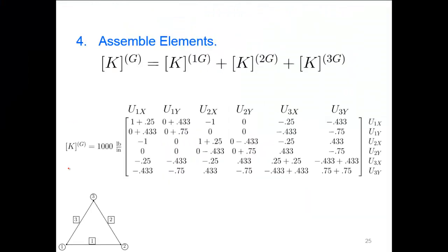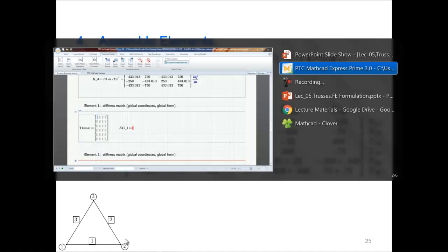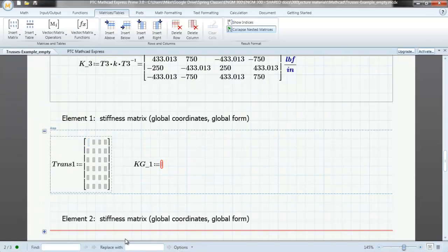Maybe let's go, yep, so we'll see right here. We've got node I down here in the bottom left corner, and node J is node 2 over here on the right. So I is 1, J is 2. If I is 1, then we can put a 1, 0, 0, 0. I'm just using the right arrow key to move here. 0, 1, 0, 0. Now we have I set up as 1.